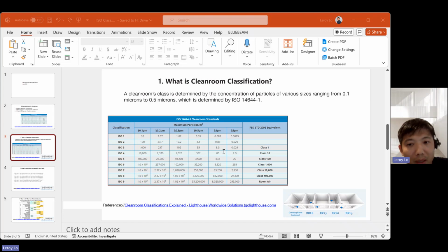Many years ago, I used to hear about class 1, class 10, class 100. The industry is changing more toward the ISO classes on the left now. For a lot of major semiconductor companies, ISO 3 is normally the baseline in the design of semiconductor fabs nowadays. This one chart requirement alone dictates how we design the clean room. It changes everything, from the amount of filters we have to the type of filter we need to use.